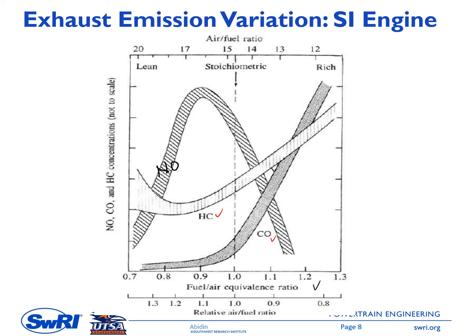As you can see on this figure, as we increase the fuel-air equivalence ratio, so it means we have a richer mixture, the amount of HC and CO pollutant increases. So you can see from this one. And then the NO emission has a maximum level at phi around 0.9.